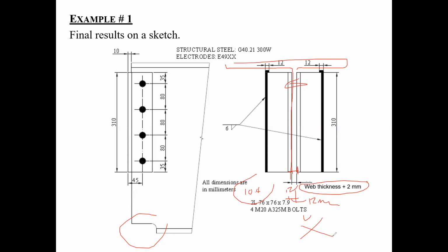Because if your gap is too far apart, when they come to bolt here, you're going to be prying those legs together, and you're going to be causing additional stresses here on these angles, which you don't want to add into your design, okay? So that's why the gap is very important. In other words, 2 millimeters is enough for them to be able to slip it in.